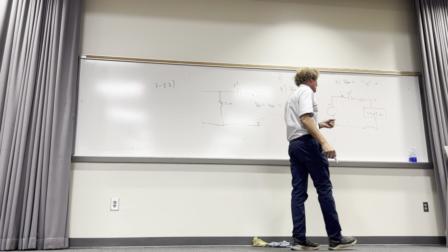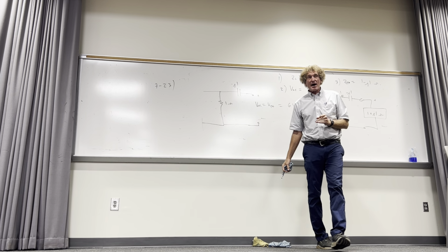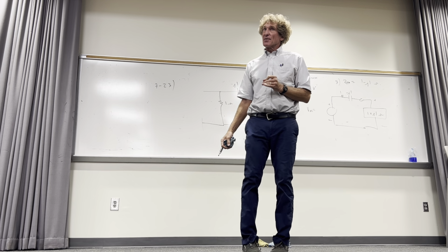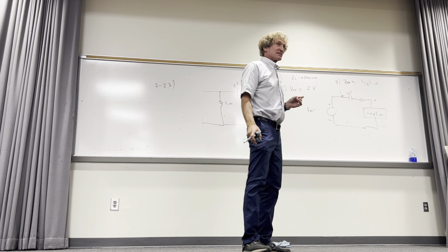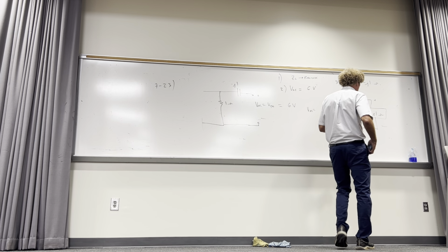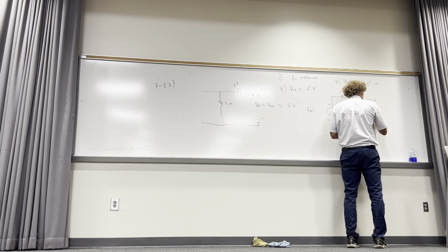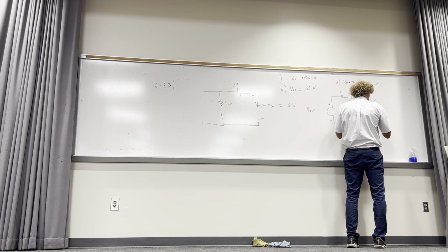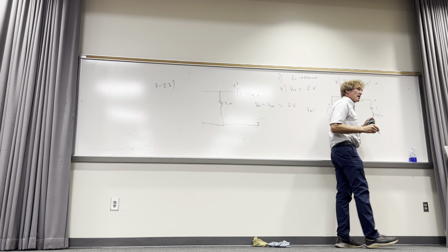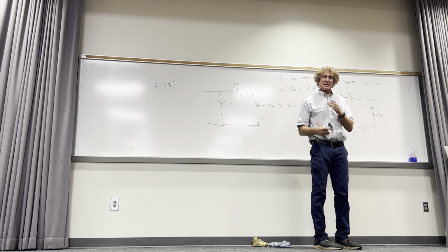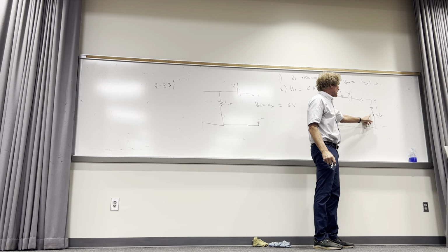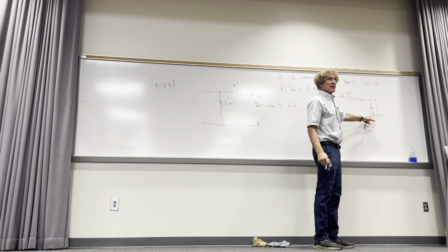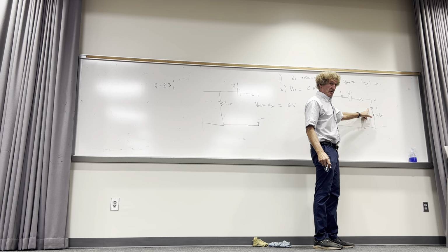So this is the value of the load impedance that would maximize the power. What is the power that would be absorbed by that impedance? Let me erase this and just show you what it is. So the actual load looks like 1 ohm plus J1 ohm, right? We want the power absorbed by that. Listen to me. How much power is going to be absorbed by that inductor? 0. Average power is 0. All the power would be absorbed here, correct?